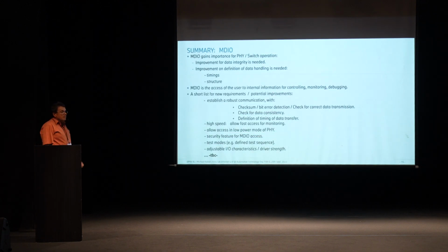Summary. The MDIO gains some importance for us. It's used for the PHY operation, switch operation, and we need improvements of the data integrity, so we should introduce something like, as I said before, some bit error detection. We need an improvement on the definition of data handling in timing and structure. And it's important for us, as via MDIO we do the configuration, the monitoring, and the control of the device. And below is a short list: we should establish a robust communication.